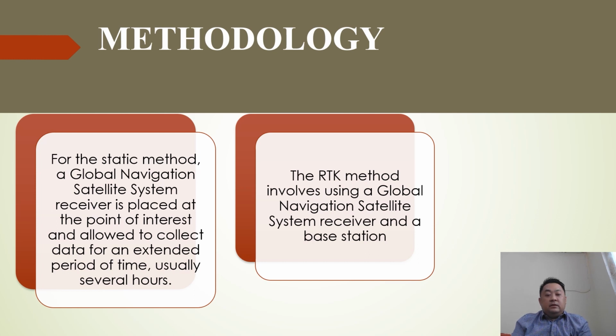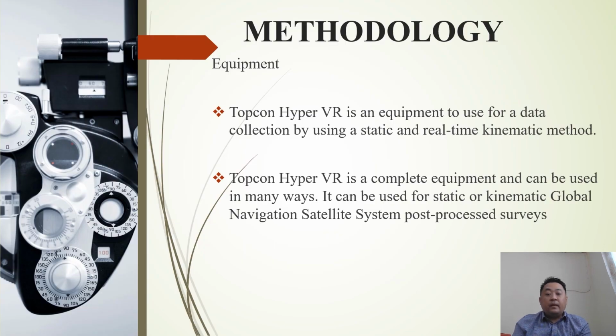Methodology. For the static method, a global navigation satellite system receiver is placed at the point of interest and allowed to collect data for an extended period of time, usually several hours. The RTK method involves using a global navigation satellite system receiver and a base station. Equipment.